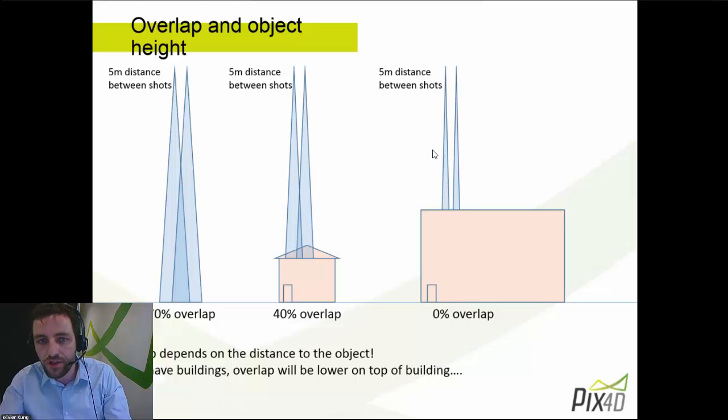Maybe the take-home message for people who are not familiar with photogrammetry from the small slide before is that everything is derived from the matches between images, because everything depends on that. And if you don't have sufficient matches, then basically the whole thing collapses and doesn't work well anymore. So the most important is to have a lot of matches. And the best way to ensure that you have matches between the images is to have overlap. And that's why we created the app, to ensure the overlap, as I mentioned in the very, very beginning.